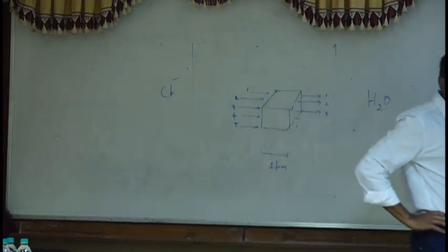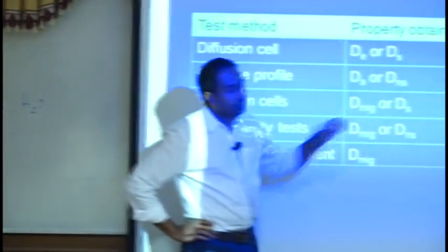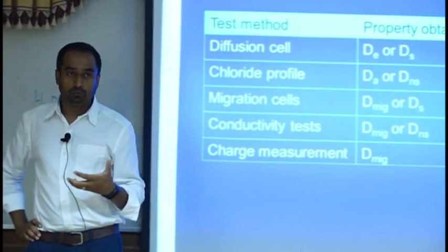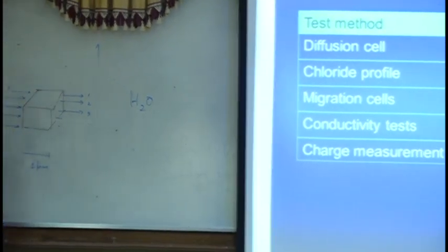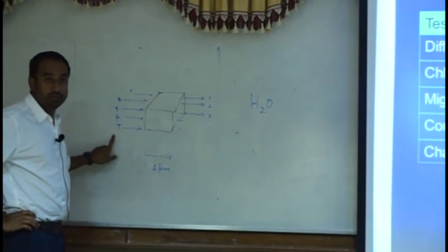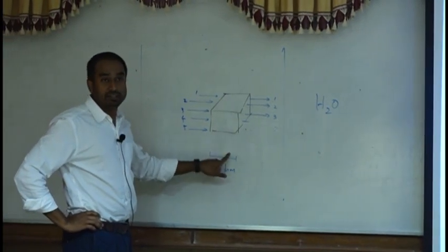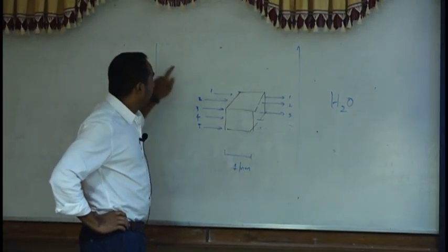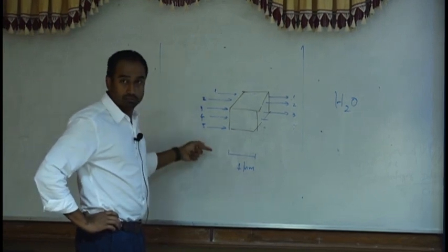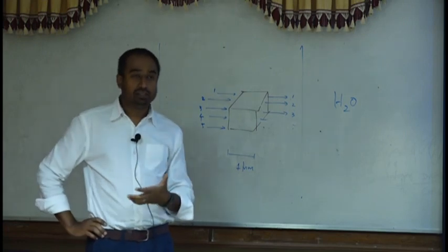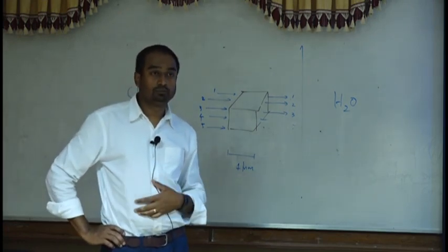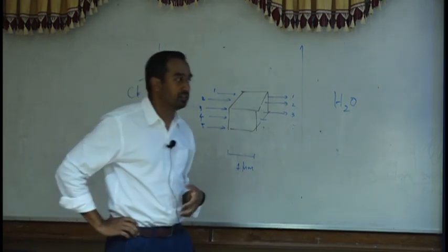This test, which you measure from the site, gives you a non-steady flow because the reaction phase is also happening. Because you're taking concrete samples at random. You have no idea whether that's in a steady state or not. So you're taking concrete samples by drilling into it. And when you plot it, what you're going to get is a representation of the non-steady flow.